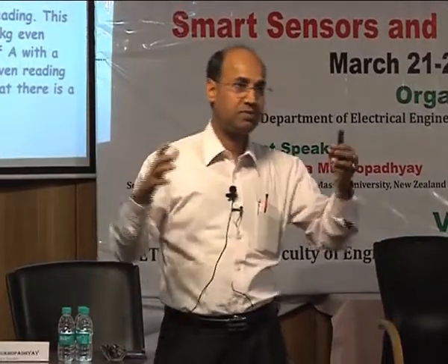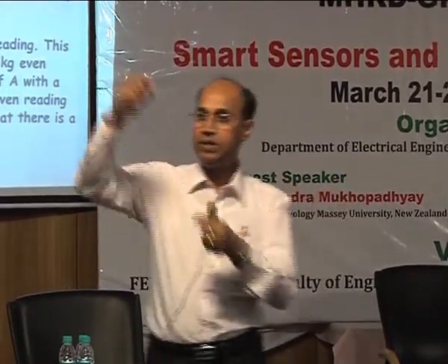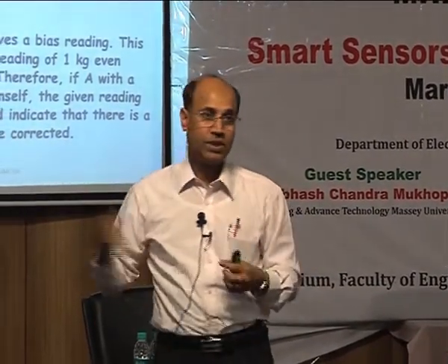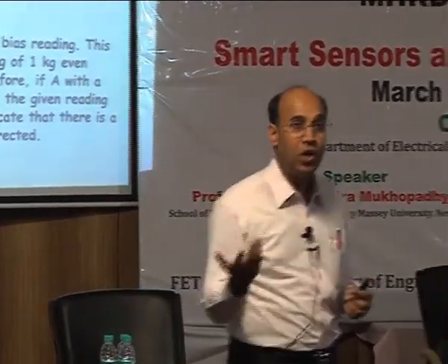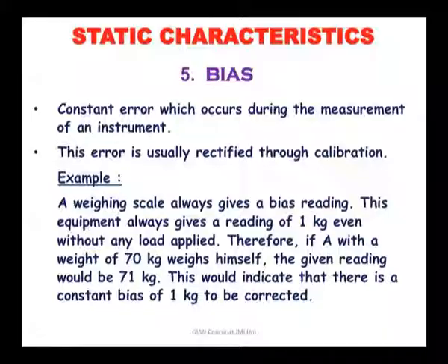Okay, and then on one side of the coil you apply some magnetic field, and if you apply current in another axis, you can get some voltage, isn't it? In that type of situation, if you do not use the biasing field, the Hall effect sensor doesn't work. But it doesn't matter for other types of sensor. So the biasing can produce some error.